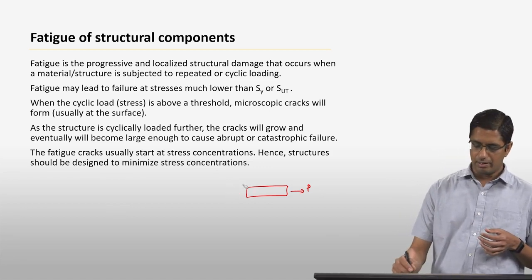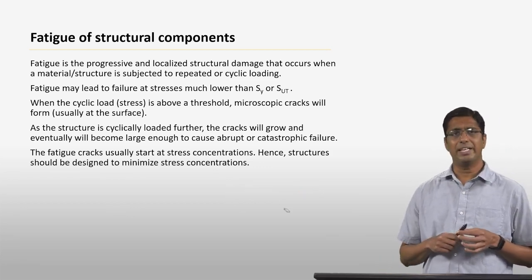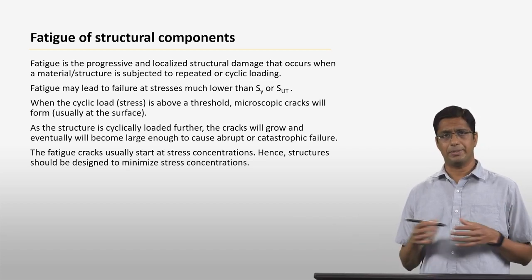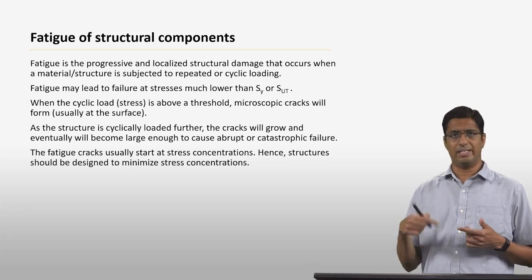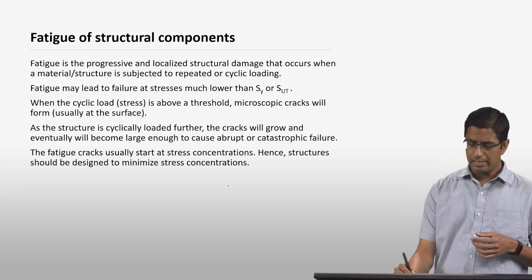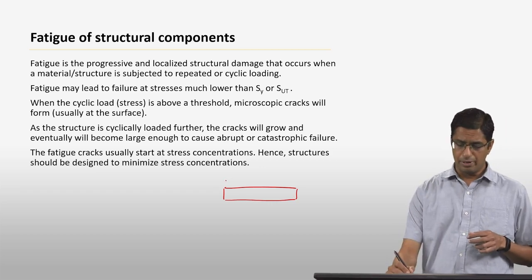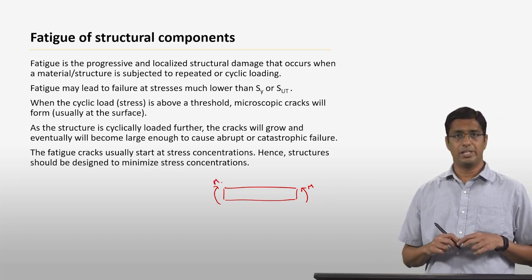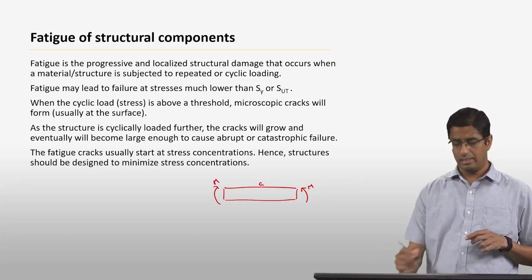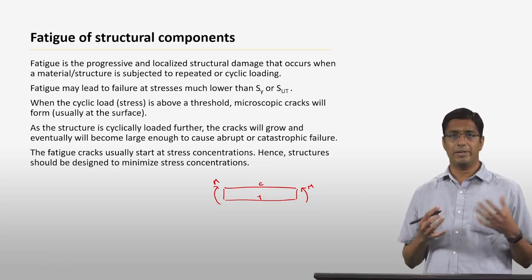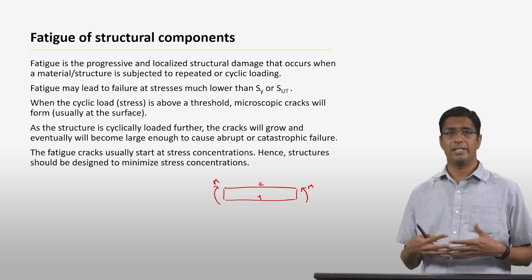In a fatigue loading, in the case of fatigue, this load is not constant or monotonically increasing with respect to time, but rather it is cycling or it is changing with respect to time in a particular manner. Okay, so if you think of, say, a beam like this, okay? So if you apply a bending moment like that, right? Essentially you will have compression in this part and tension in that part, okay? But then the points where you have compression and tension are essentially going to stay the same with respect to time.